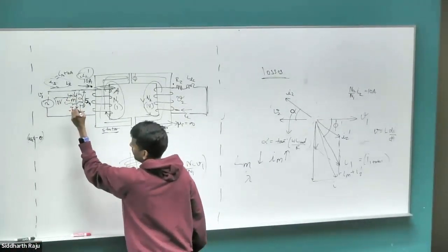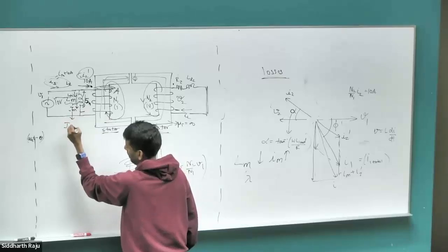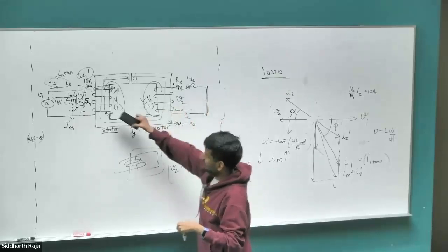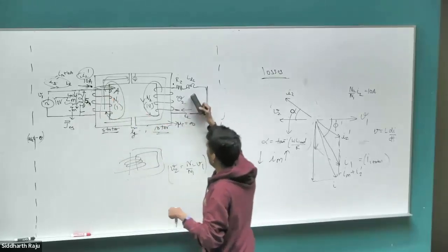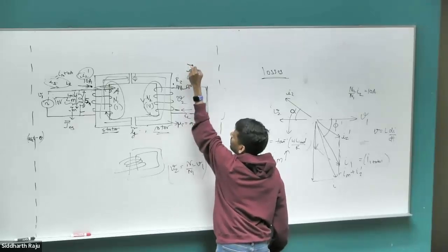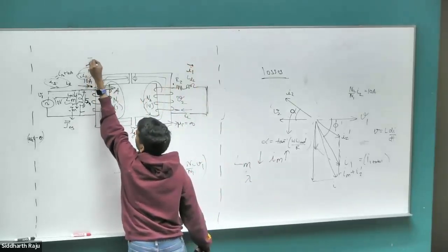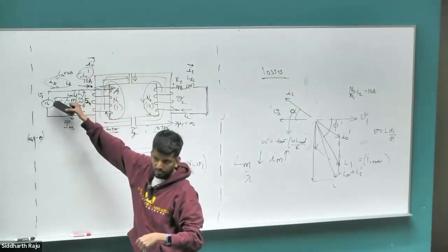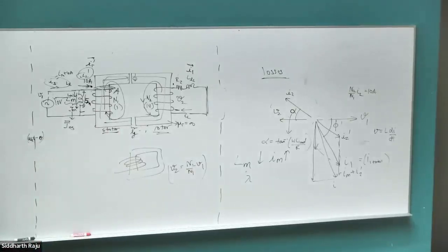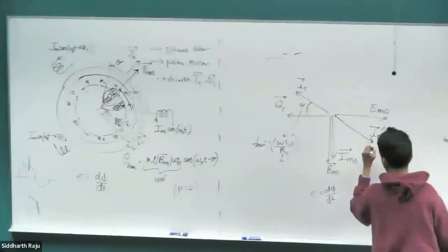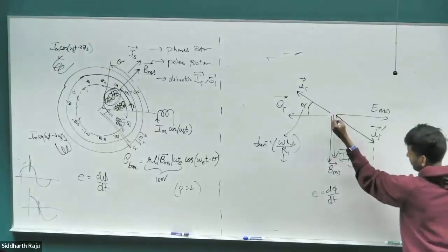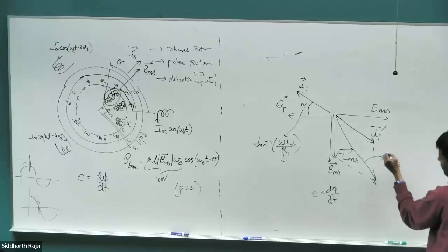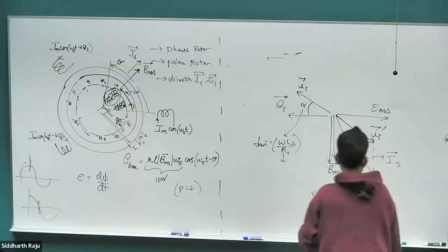This IM is the same as our IMS space vector in the diagram. Right? And then we had some I2 current here. The reflected current of that was I2 prime. In our case, we have rotor current IR here, and then the reflected rotor current on the primary side. The sum of these two currents is the net current being drawn from your power supply. So the sum, like this, is going to be your net primary current drawn from your power supply.